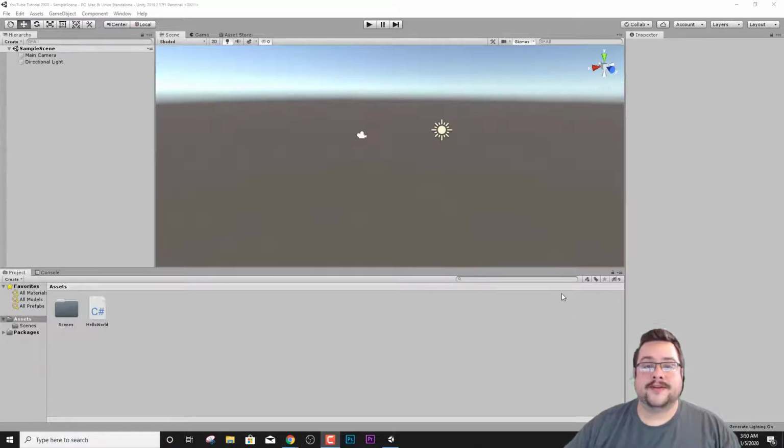Welcome to our third episode of our Unity tutorial series. In our last video, we went through how to create a C# script, a very basic one, but a script nonetheless, on how to print to our console. In this next tutorial, we are going to start adding some actual 3D objects to our scene, including our ground plane, and we'll see how far we get. We might add a first-person controller as well, so we can run around our scene. But for now, let's go ahead and create a plane for our game scene.